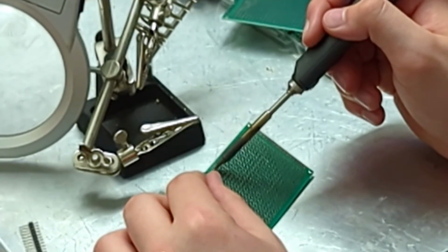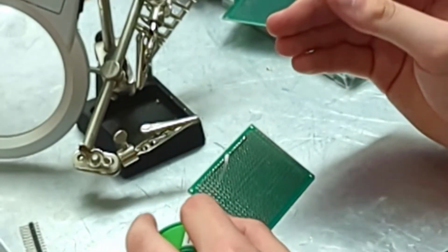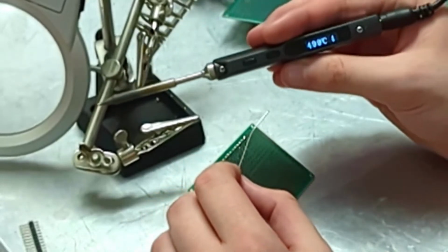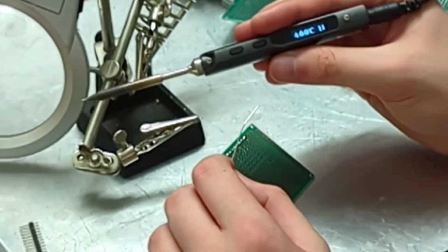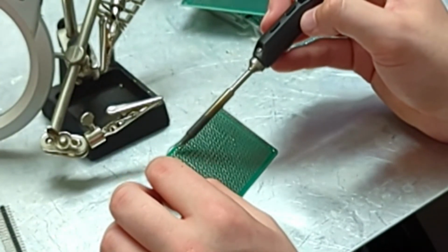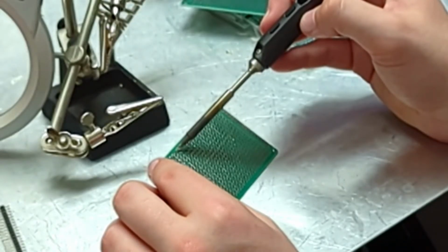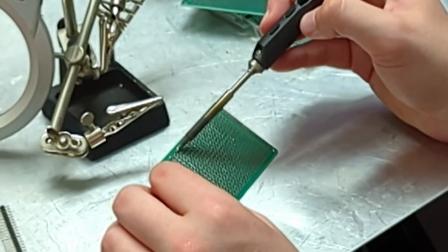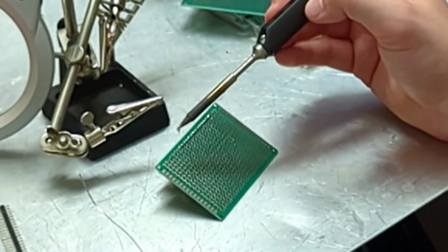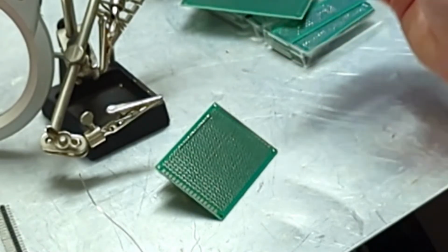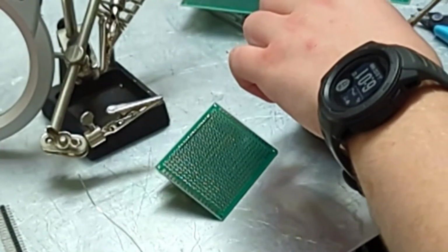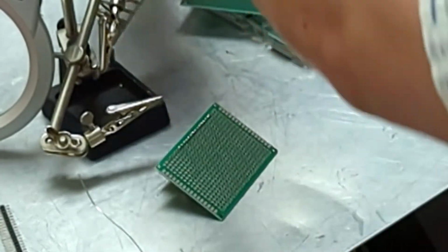The trick to soldering lots of little pins like these, I found that the highest heat my soldering iron goes, 400C, works well. Additionally, what you want to do is you just want to touch it just slightly, and then you don't want to put your solder to the soldering iron because what just happened there happens. What happened is the solder all went straight to the iron and not to the actual pin, which isn't good because then you're not soldering anything, you're just kind of wasting solder.